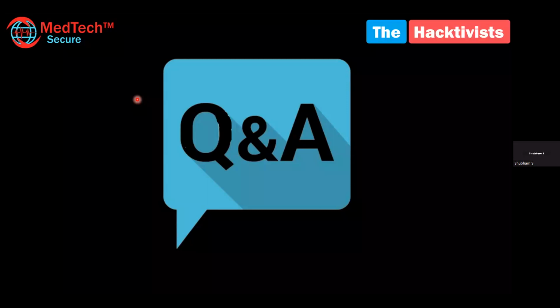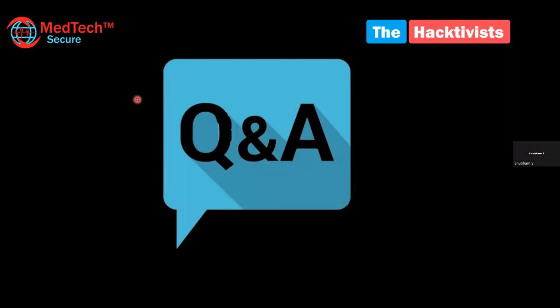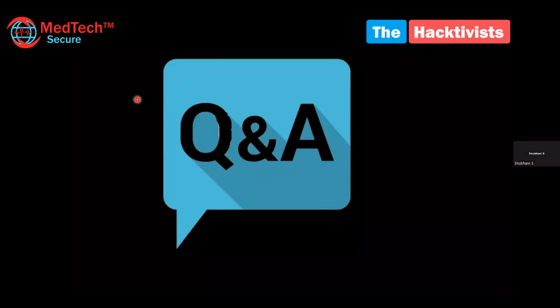Hi, my question is related to firmware reverse engineering. As per my research, the firmware can be in a Linux kernel or in an RTOS, so I wanted to ask from both perspectives. If the Linux kernel firmware is in a .lmp file format and it is encrypted, and in Binwalk it shows that it is encrypted or doesn't show any file system, and if we use EMBA or some other tool and it is able to decrypt the file system in a layman format and I can only see a few files, then what else can I do to decrypt the whole firmware and get more out of it?